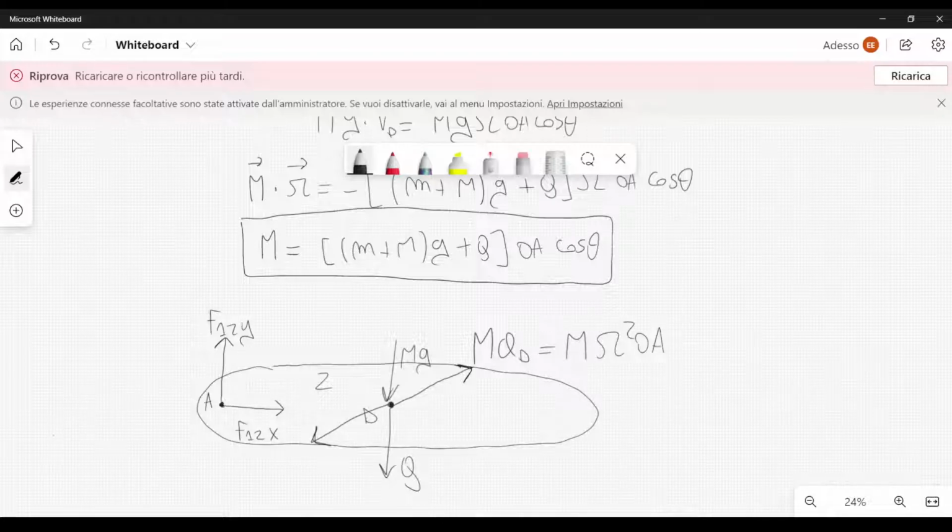And the acceleration of the point A can be obtained by considering the first rod. And this point here, the point A, is accelerating inwards. So it is accelerating with a centripetal acceleration that's directed along this line OA. So it's going towards the point O. And we don't have another component which is perpendicular to this one, simply because omega is a constant.